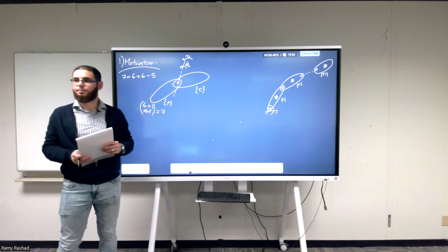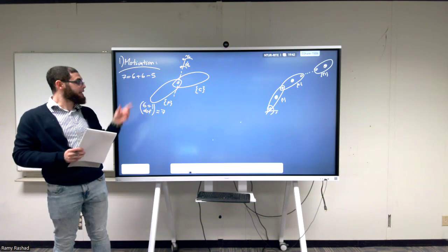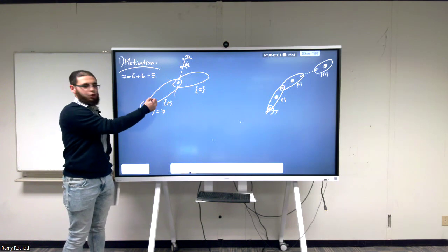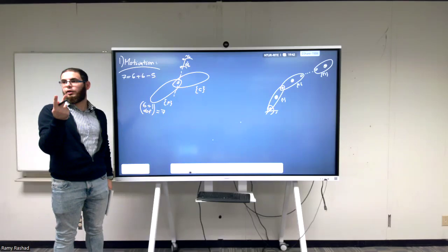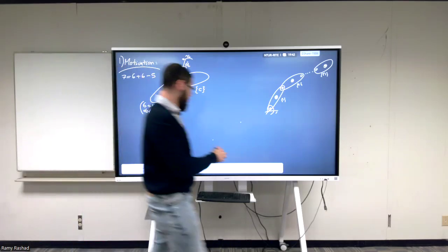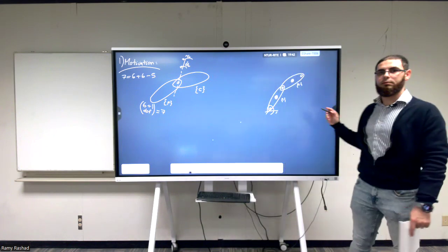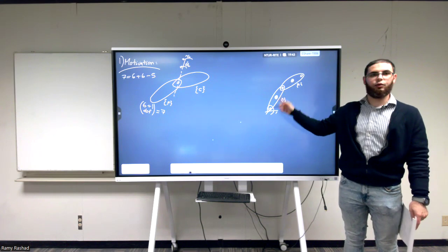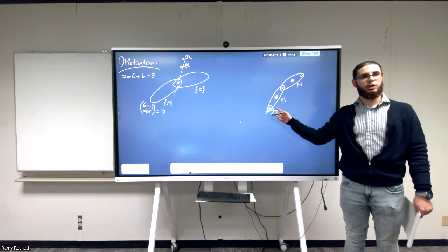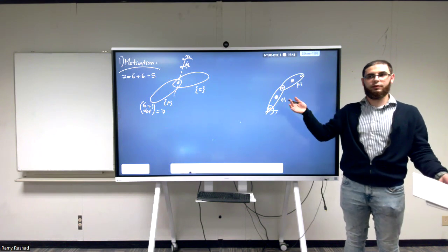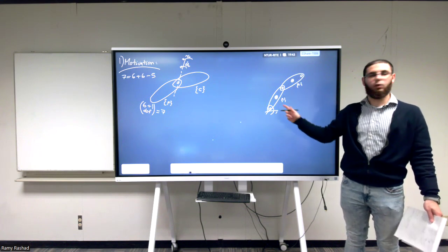Instead of fixing it to a base, cancel out to the 6, and then it's reduced to 1. Exactly. If you add another link, add another joint here, then the 7 will be reduced by 5. You're going to be having 2 degrees of freedom. And this is the picture that you imagine, right? So if I give you this robot, for example, and I ask you how many degrees of freedom does it have? It's only 2, right? Theta 1 and theta 2, right? So it was 6 plus 6, and then I had 1 joint and 1 joint, each of them reduced 5 of its own. Then I had 12 degrees of freedom minus 10. I'm left with 2 degrees of freedom, theta 1 and theta 2 here.